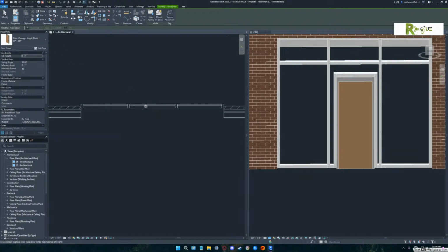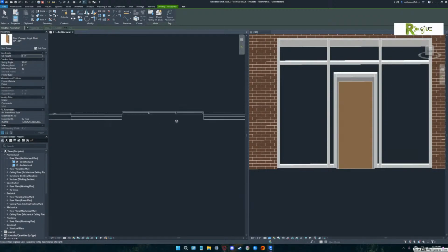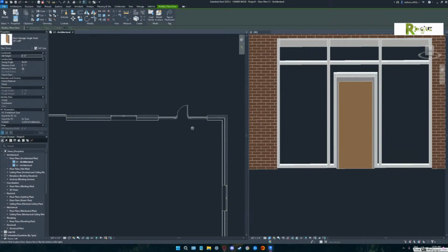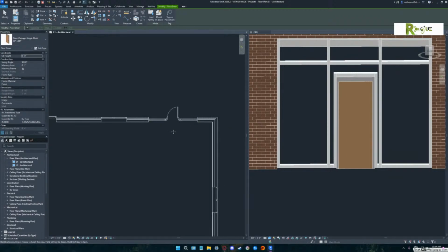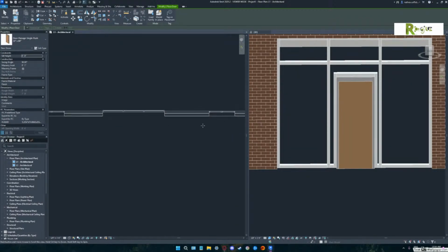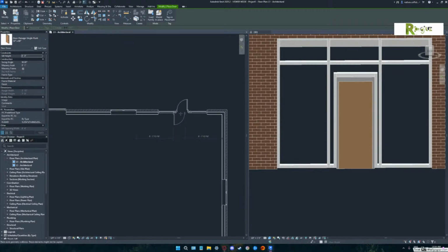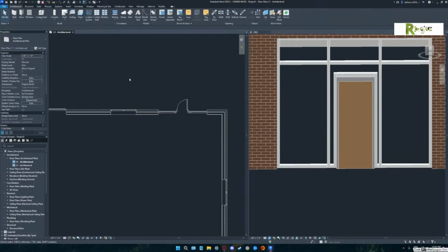Okay, no, you can't. It actually put the door in the wall that was containing the curtain wall. Interesting. That would really confuse someone. Do you see how you cannot put a door in a curtain wall? So that typically is going to make most people say, well, I need to use doors and windows. And as I said, it will be 2-3 years before you realize that that's a bad idea.